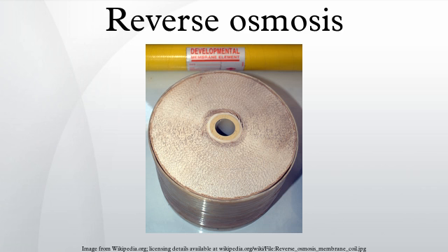Disadvantages: household reverse osmosis units use a lot of water because they have low back pressure. As a result, they recover only 5 to 15% of the water entering the system. The remainder is discharged as wastewater. Because wastewater carries with it the rejected contaminants, methods to recover this water are not practical for household systems. Wastewater is typically connected to the house drains and will add to the load on the household septic system. A reverse osmosis unit delivering 5 gallons of treated water per day may discharge between 20 and 90 gallons of